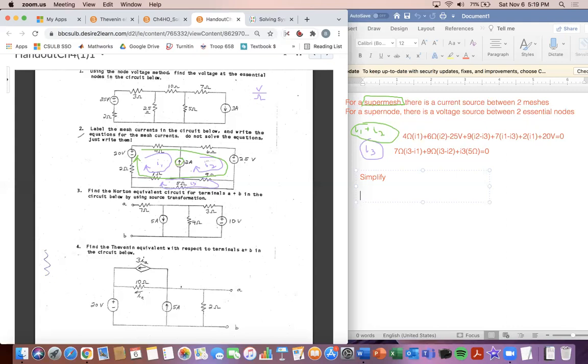Okay, you're thinking of power. If the current goes from the positive to the negative terminal, it's a voltage drop and positive power. But if the current goes from negative to positive, it's a voltage rise, and that would be negative power. This is a different application, where we're doing mesh currents. You know how I drew this loop right through here?